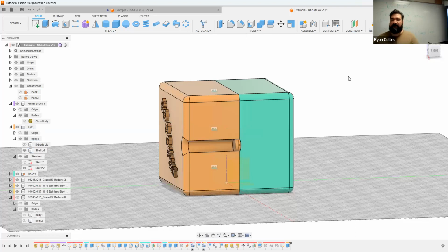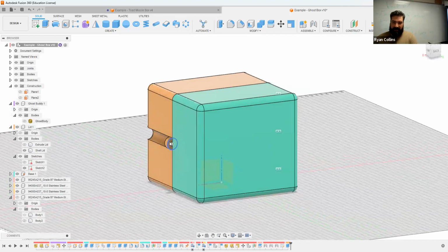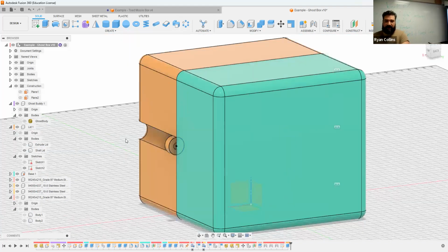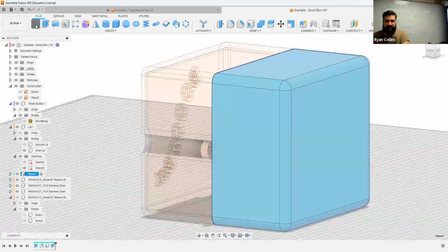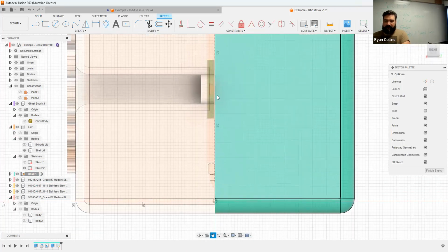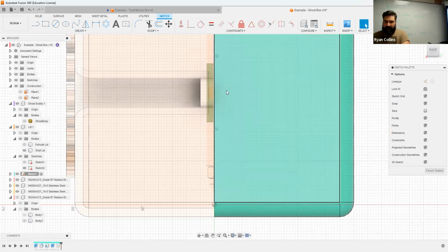We're not adding anything complex, just a little feature. And frankly, I can even expand it off of this little chunk here. Might have to tweak some stuff, might have to make this little thumb catch a little bigger. So first, let me activate the base, create a sketch on this front face. And all I'm going to do is create a little hemisphere right off of this top.